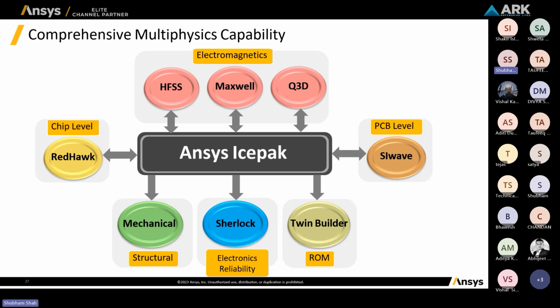Coupling with other tools also indicates the different physics. Let's say you are performing the Icepak Classic simulation and you want to go with the coupling of electromagnetics, or you want to come from the PCB level, you can take the results from there and perform your simulation in Icepak.